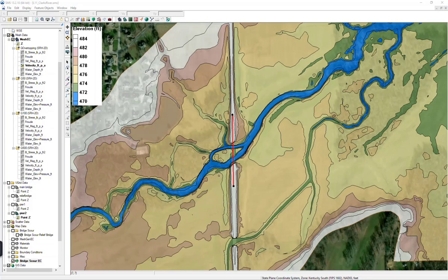The arc is generally drawn along the center line of the roadway embankment, and in some cases where the flow is still contracting through the bridge opening and we have higher velocities near the downstream face of the bridge, it may be prudent to draw the arc closer to the downstream face. But for this case, the center line approach appears to be fine.